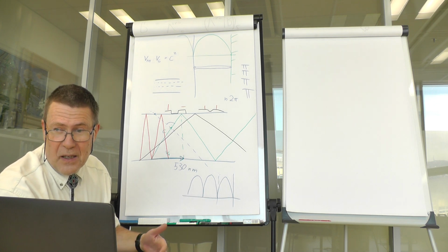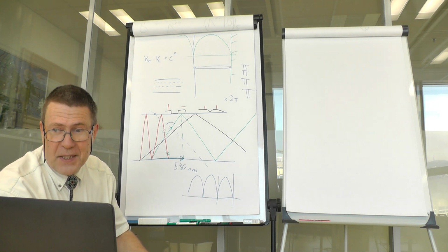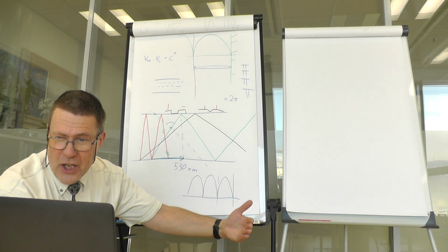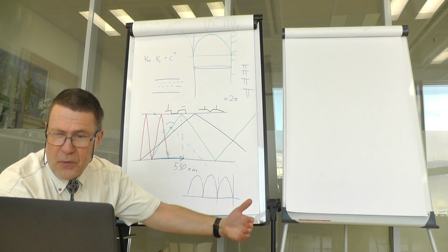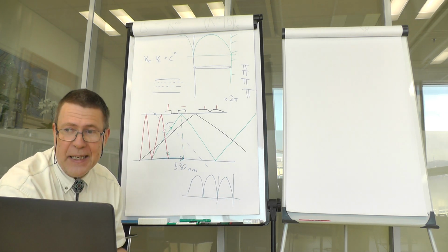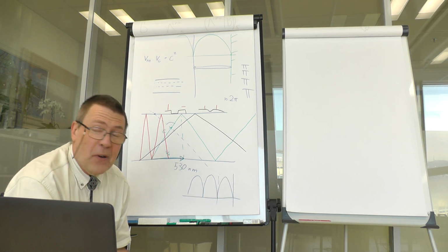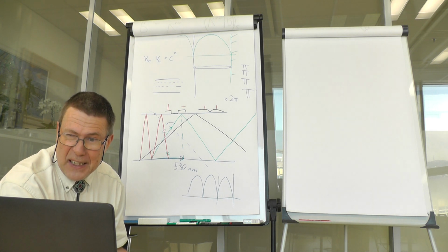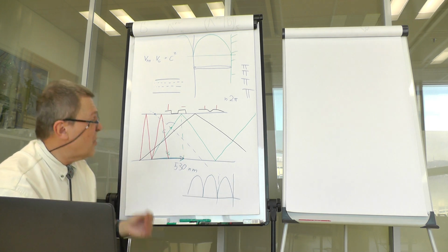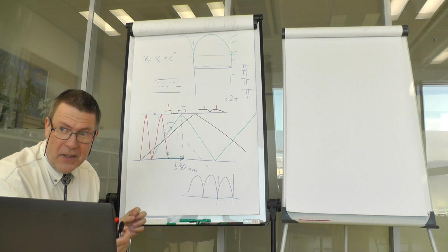So if you create some complex modulation, then after some length of travel, the signal changes due to the dispersion of the line. You can, of course, use a very narrow band signal, but then you have a limited transmission capability as to information transmitted through that signal. So that's one of the problems that inherently come with this kind of lines.